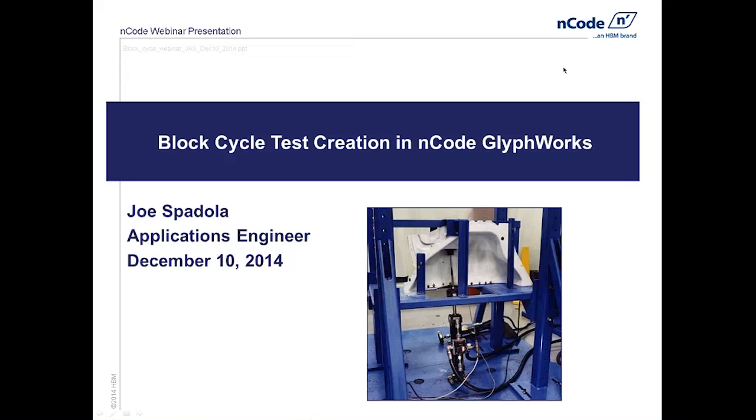And what we'll find out is that we can do that by establishing a common link that makes theoretical sense from a fatigue perspective between the customer usage data and our simplified test. I'll go ahead and spoil the surprise right now: the common link we're looking for is damage. We'll be using GlyphWorks to calculate that damage and then to ensure that this newly created test spec contains the identical amount of damage as the customer usage data.